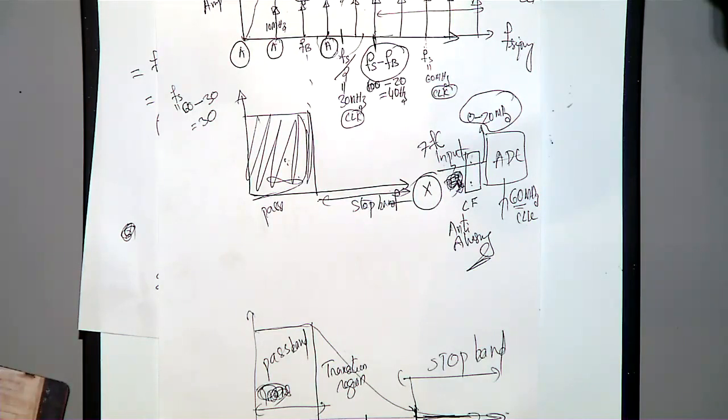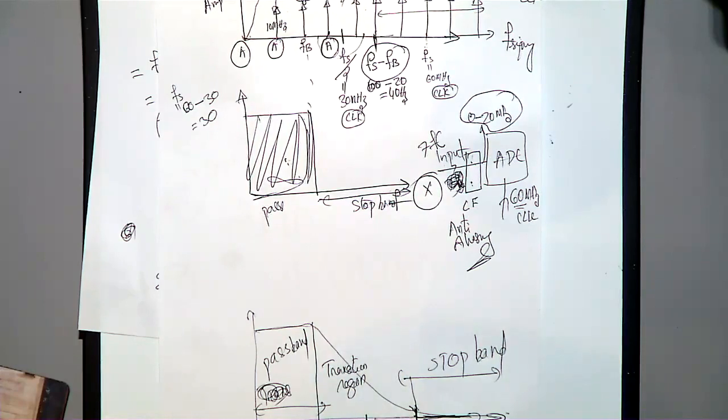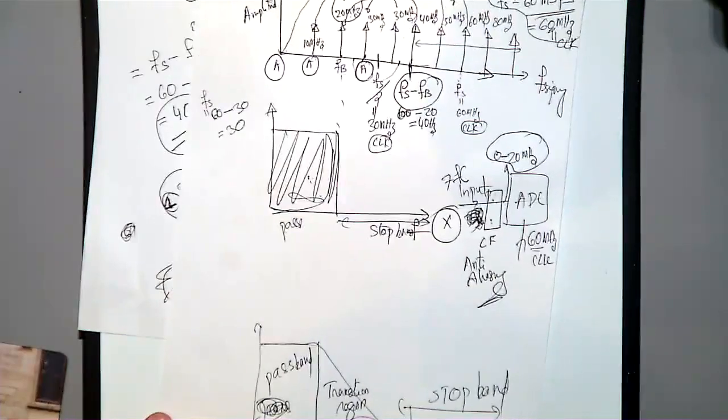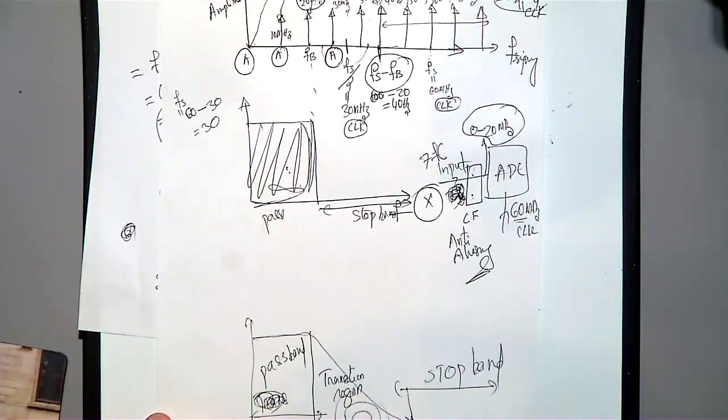So then in the transition region, what is happening? In the transition region, this frequency will appear here. This frequency will appear here. But amplitude is decreasing, so that's okay. It is attenuating. So whatever is coming here, definitely after the Nyquist frequency, your errors are coming, but that is coming in this region. It's not folding back to your pass band.